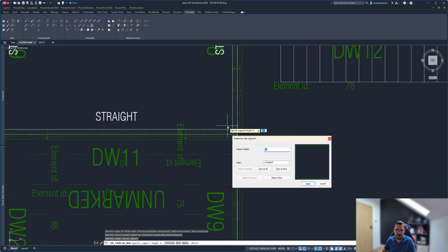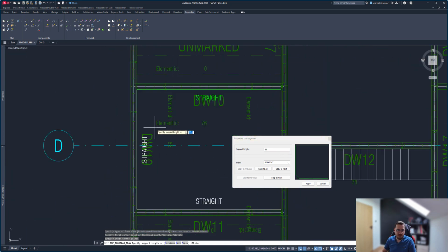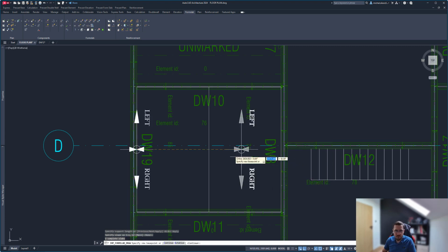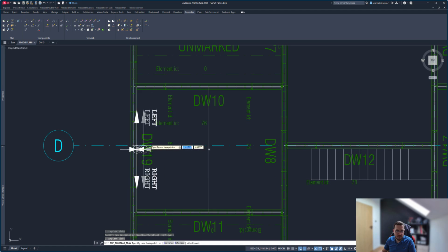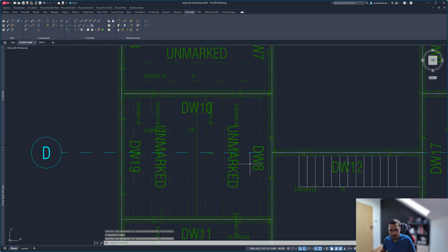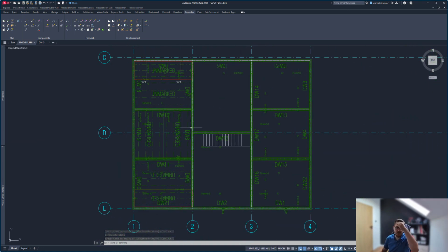You can just extend your slabs, for example, to the ends of panels, and then just have 0 on support edge. But what I'll do here, this is going to be 0. This is not. Step to next, 80. Step to next, and 0. Yeah. Right, no slope. And for example, we can leave it like this. And this actually makes it fit 2 slabs perfectly with no cuts in this direction.